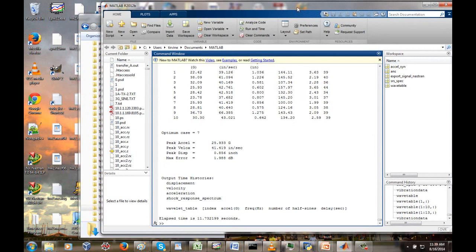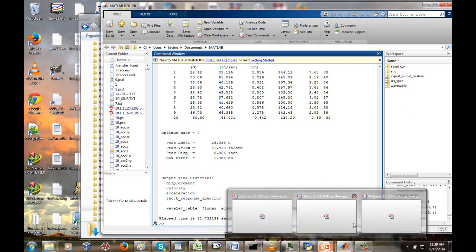And hopefully it's repeatable too. Anytime we're dealing with shaker shock systems, there's always the potential problems of fixture resonances and other things going on with that shaker test system. But in many cases, this can be a very stable and just really good way to go for performing that shaker shock test.